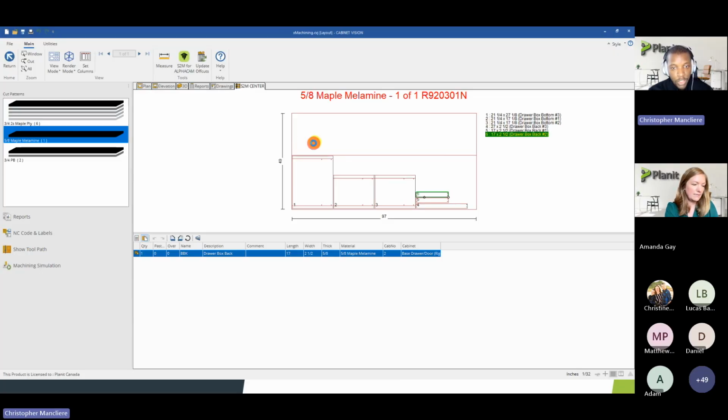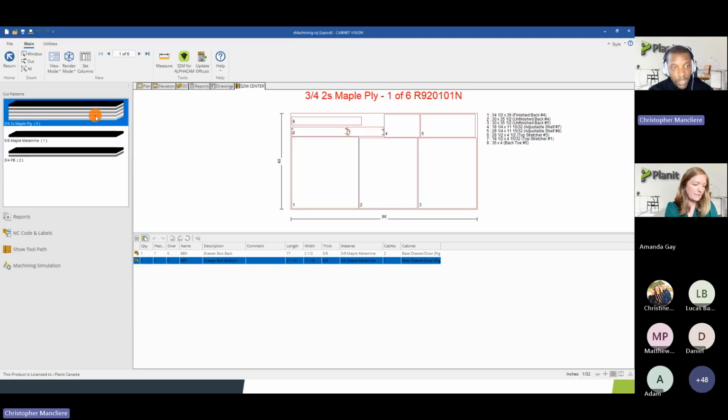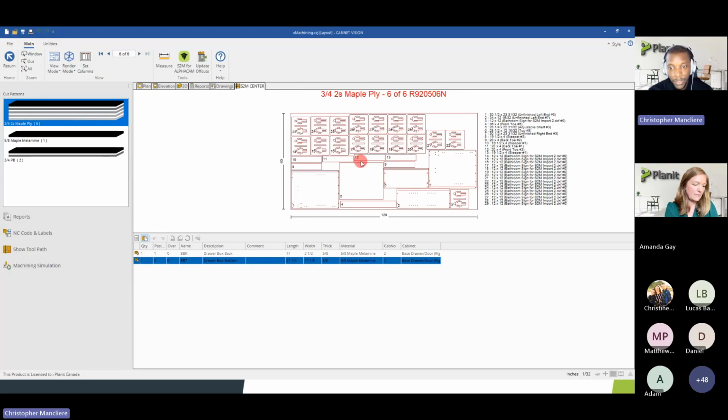And then you can drag and drop your part. And in this case, I just don't have the space because it's part of a group. But you can drag and drop it, and you will reinsert it in your nesting. When you have the clipboard, you can add as many parts as you want, so you can copy and it will just be added and waiting for you to insert it wherever you want. What you can do too is when you want to add a new sheet, so let's say I have those 6, but I forgot something or I want to copy something, you can right click directly on the stack and you have an option to add a blank sheet.